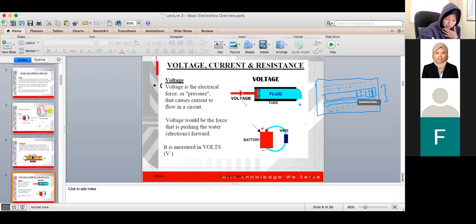That's why when you want to connect components on the breadboard, you have to connect them vertically, so that they connect to each other. But for the holes at the side, they are connected to each other horizontally. So if you want to connect one point to another point, you have to connect horizontally. Do you understand? The breadboard that you use in your lab.